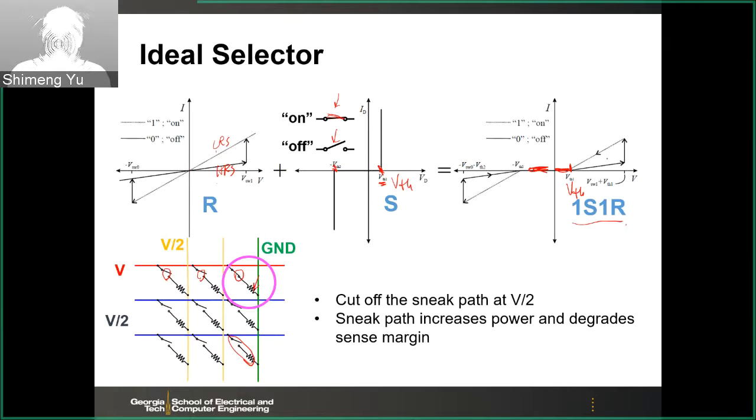And only above the threshold voltage can you differentiate your LRS and HRS, the two resistance states. The advantage is that if you design carefully, and this is not to scale, if your half V, V over 2, is below your threshold voltage, then the half selected cell will be cut off.